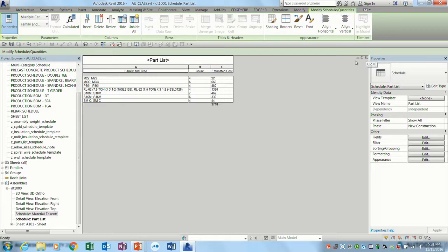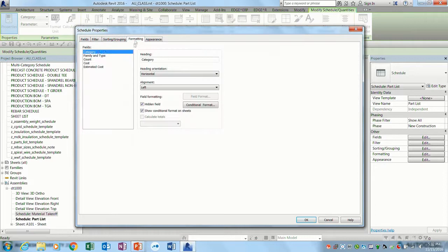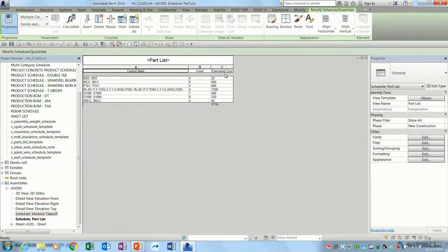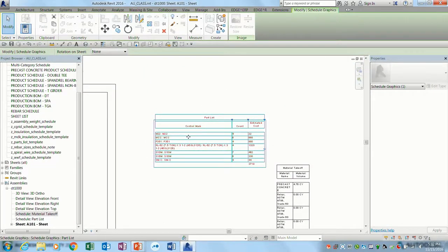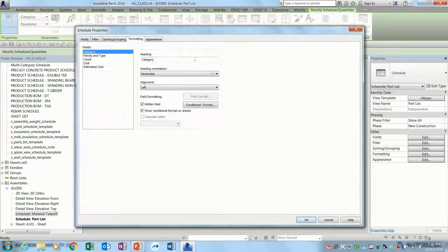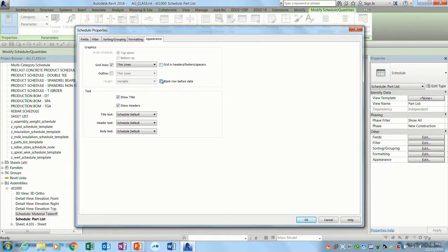So we've got a schedule that's a product schedule, and as we're adding double T's, it's just automatically filling that up for us. Anytime we want to look at it, we can look at it, see what our estimated cost is, or our estimated total concrete is, or whatever those things happen to be. We're in a good position to be able to immediately extract information once we've modeled it. So this is what I'm going to call a Revit template as opposed to a view template.